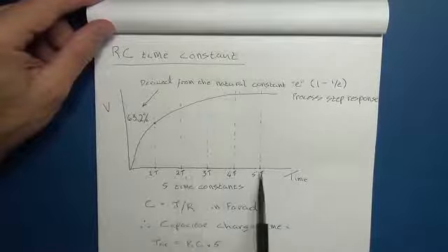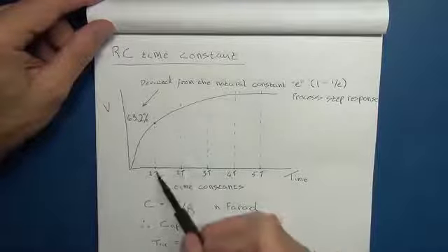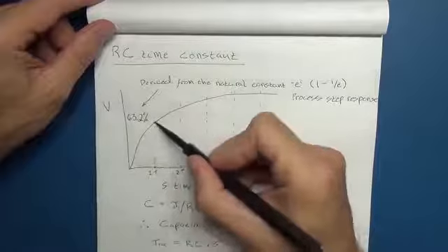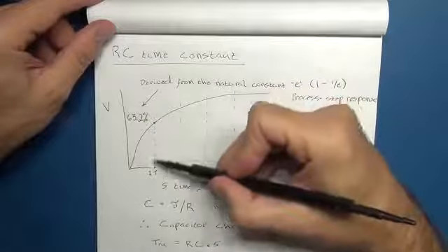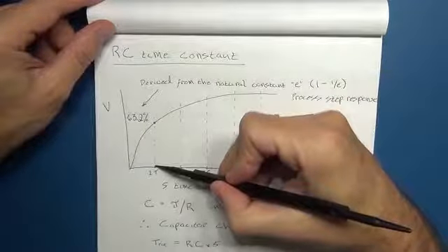You've got 5 of those, but you only need to use the first time constant to do the calculation to work out the capacity. To find that time, you take the charge time: once your charge gets to 63.2% up your curve, that is where you take your time constant from.